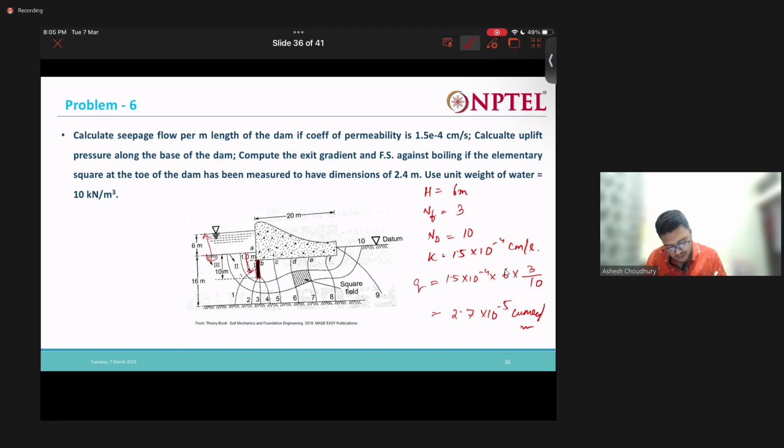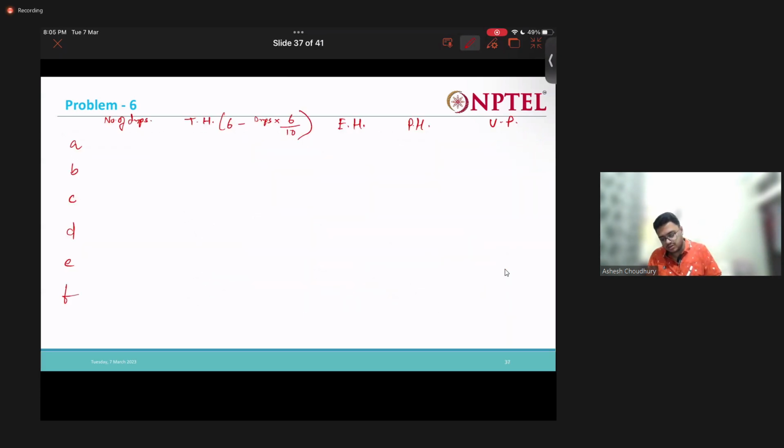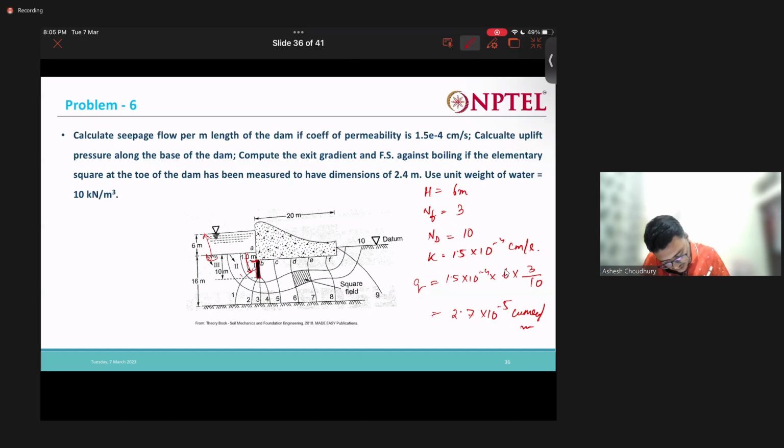So approximately we are taking that 0.5 drop is occurring. Just approximate. For the point B, B is here. So one drop here, 2, 3, 4. This is the fifth drop, but my B is here. So approximately we are taking 4.5, between the fourth drop and fifth drop.